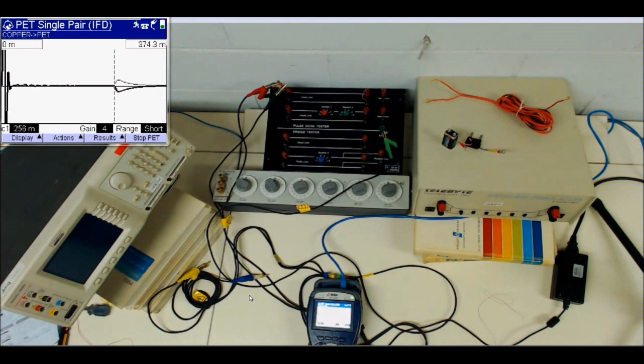What is basically IFD? It's a function that allows us to keep the previous graph compared to a new graph. So whatever phenomena are happening to the line and we are not being able to see them before this one happening, it's like keeping the previous trace and doing a graphical comparison with a new trace. In this way we can clearly identify ghosts or even intermittent mistakes that are on the lines and we cannot pick them up at once.